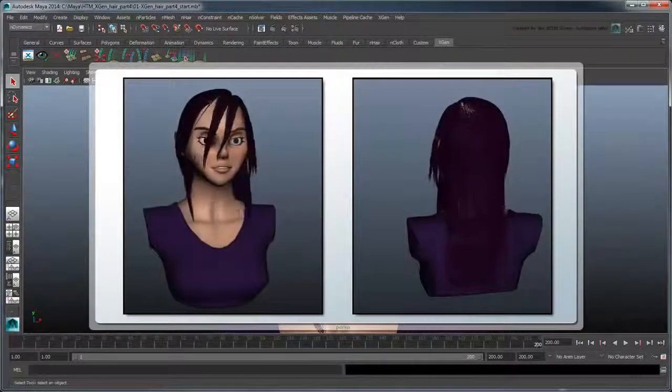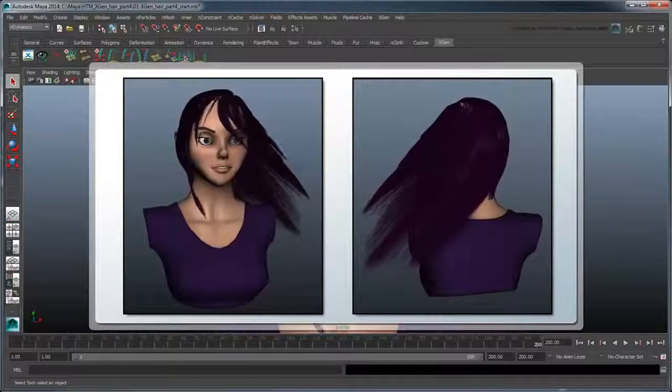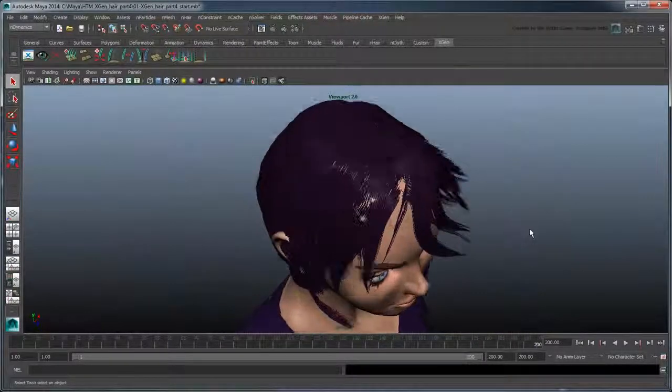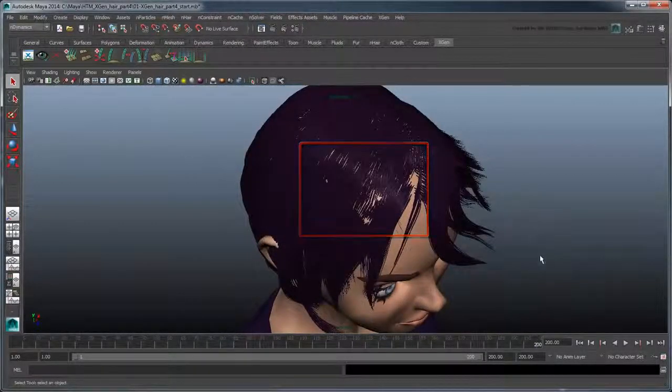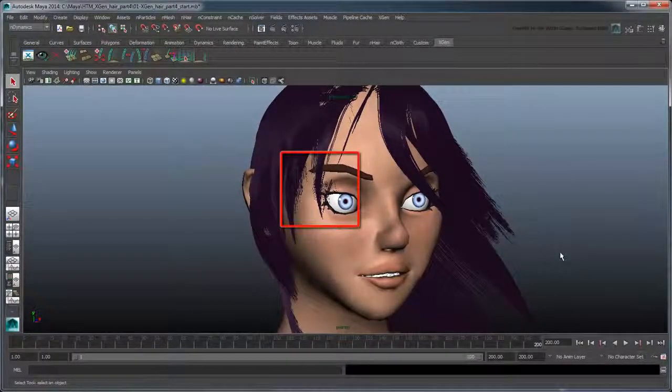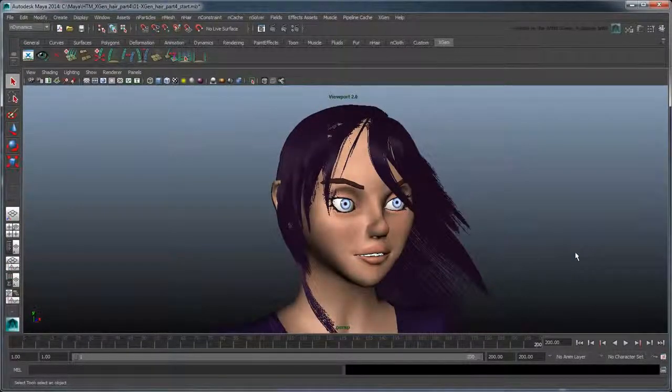As you can see, breathing life into your XGen hair through nDynamics is relatively quick and simple. However, you'll notice some of the hair penetrating the bust, despite the fact that it's a passive collision object. Fixing a problem like this can require more granular control over the nHair generation process, as well as the simulated collision steps than this top-down approach can give us. In the next movie, we'll animate the XGen hair using a bottom-up method that will afford us this greater degree of control.